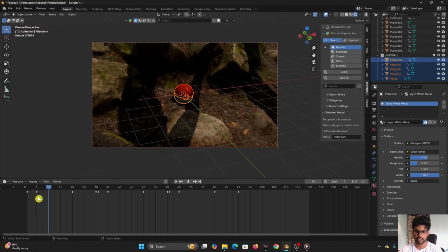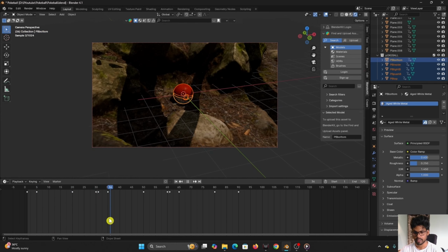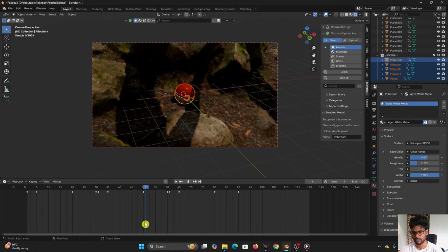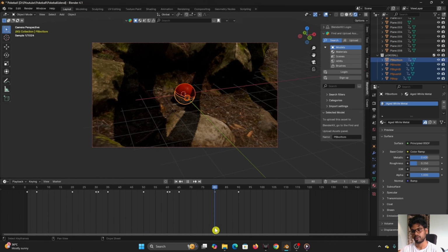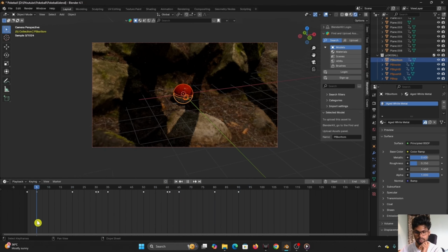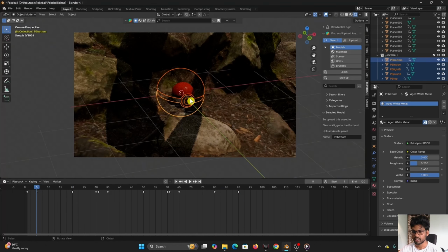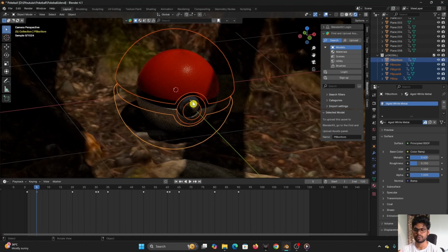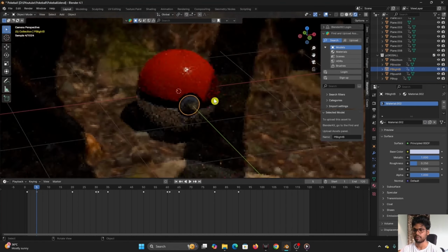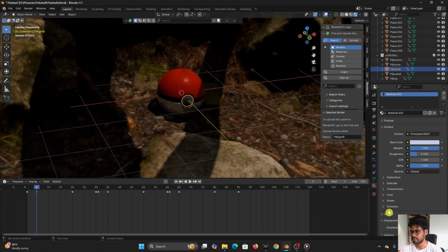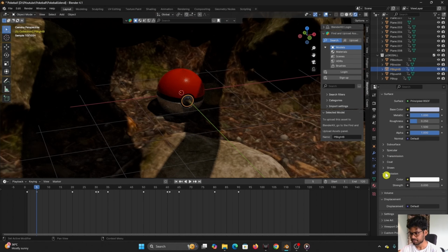and this is when I want the emission to start. So on frame 5 to 20, and then 35 to 50, and 65 to 80, I want it to be on red, and then I want it to turn green. All right, with on frame 5, I'm going to select material, and this time, because you only want to add emission to the light up button, I'm going to click on the light up button and go to materials and click on this emission button that you'll find in the material section.